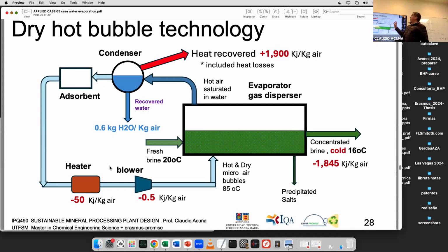It's not that complex, because if you know the conditions here, humidity and temperature, you have the enthalpy directly using the psychrometric chart. Enthalpy means how many kilojoules of energy you have per kilogram of dry air. Working with air is a lot easier, so the psychrometric chart is really, really good. Okay, super easy. In the first stage, you mentioned that about 2 to 3 degrees that we can recover.